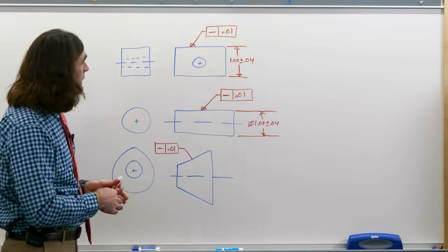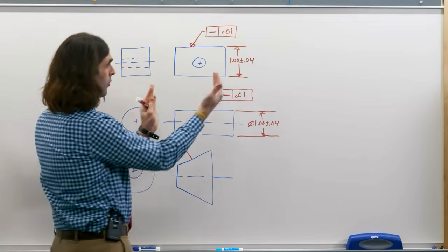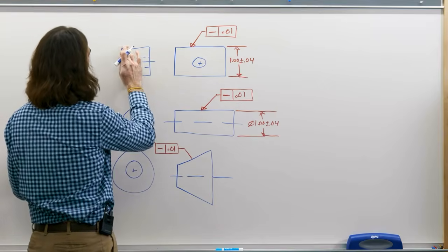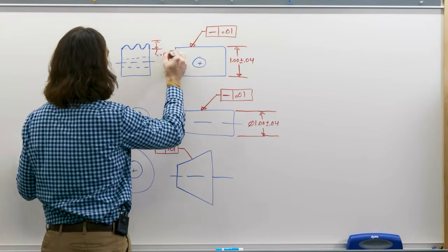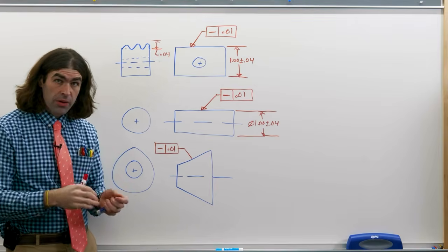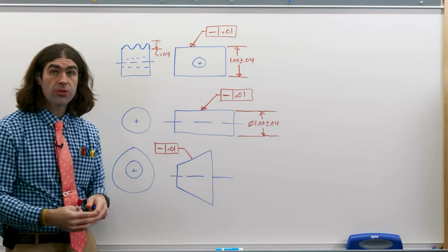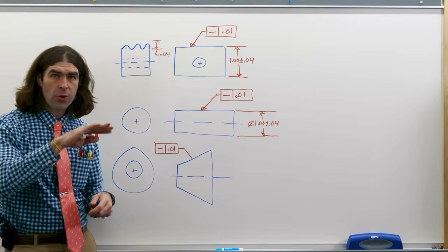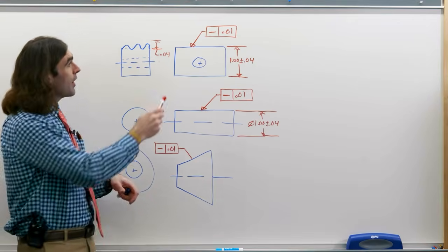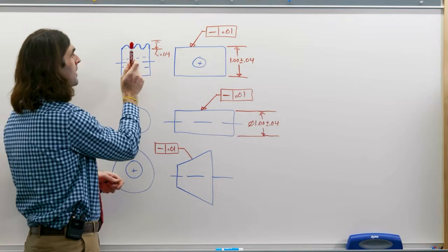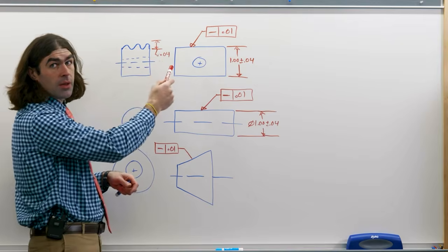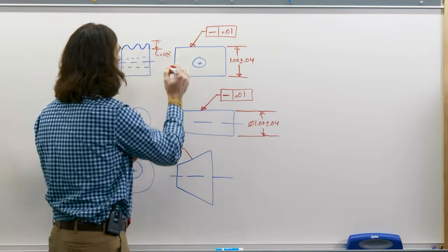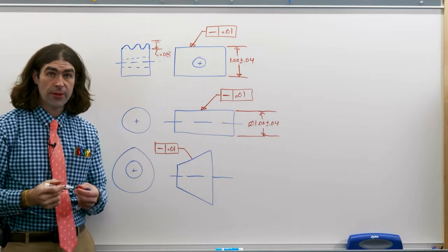What that means is that on the right view, so front view, right view, on the side where the straightness doesn't apply, you can use the full size tolerance for that feature. So you can end up with a corrugated roof shape. It's got to be straight in this direction, but not in this direction. This can use that full 80 thousandths of size tolerance.